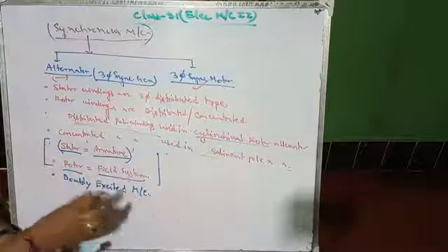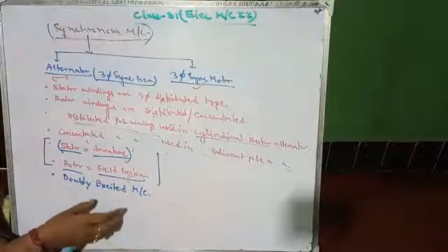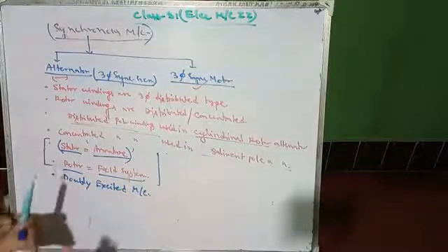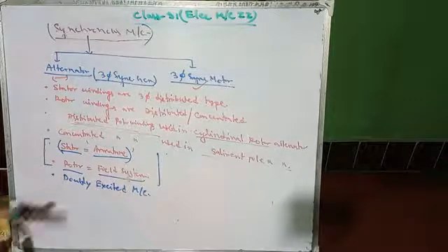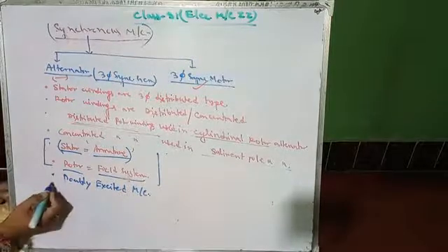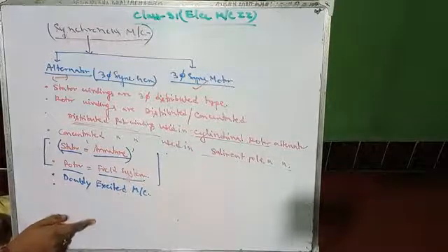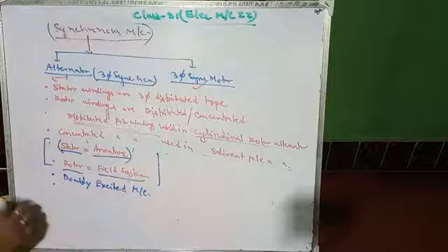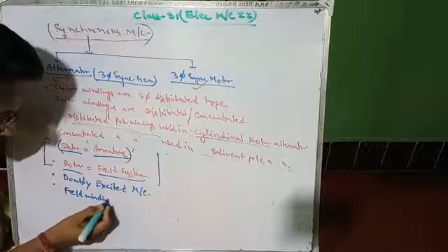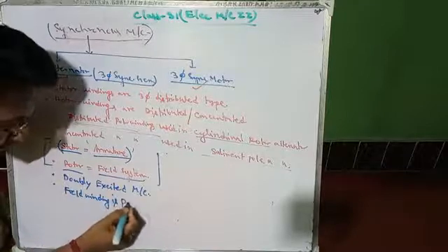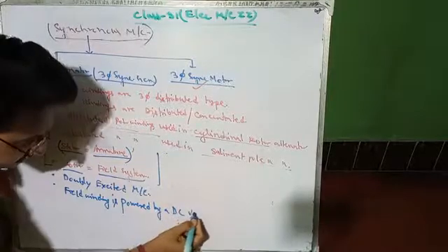Mechanical energy is given by the prime mover to the rotor part, and simultaneously an excitation system is required to excite the field. So that's why it is called a doubly excited machine. Next, the field winding is powered by a DC voltage source.